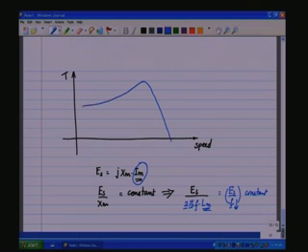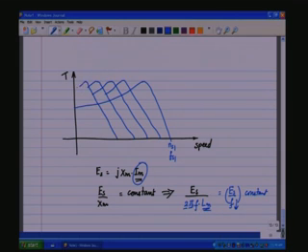So we saw that the torque is like this for, let us say, some ns1. This is at fs1, and then as fs changes, we have a family of curves with the operating points getting shifted in this manner. This is ns2, synchronous speed 2 at fs2, ns3 at fs3, with the frequency reducing to 0. So you see that you could operate it as almost a constant torque mode up to the synchronous or the base frequency.